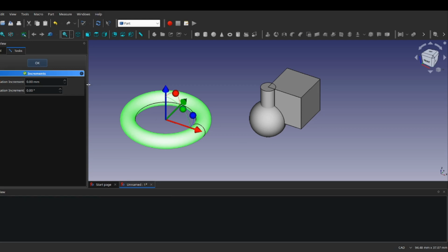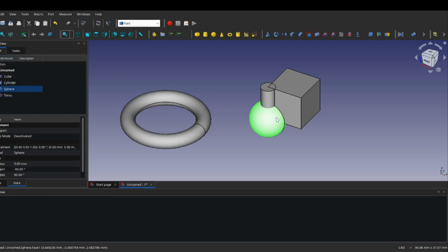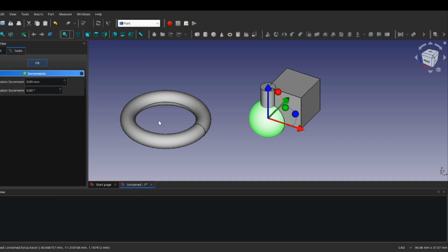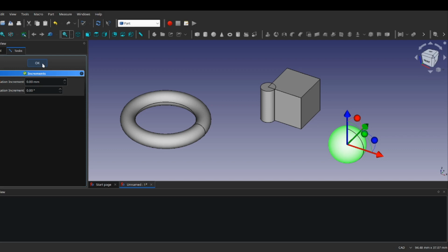In Freecad, you then have to choose OK to say I want it there. OK. For the sphere, I want to move that. Let me go up to my View and see if I see Transform up there. Yeah, here, Edit, Transform. There it is again. So you've got two ways of doing it. In Blender, you move it and that's it. Here you have to say, okay, I want it there.